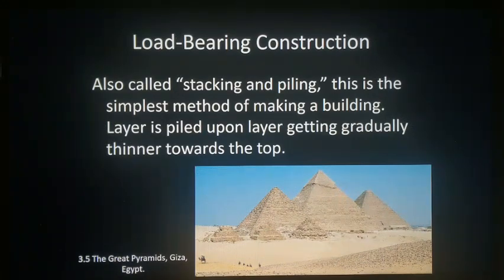The stones are placed one on top of another, and we're starting to get that inward slant on the walls as it moves up. We never see any of these structures in the form of a skyscraper, for example, that has a right angle in its departure from the surface of the earth. It is important to think about the way that this works. Whenever we have materials that are very heavy like this stone, you have to begin to move it inward as you go upward in height. Otherwise, you risk collapse.